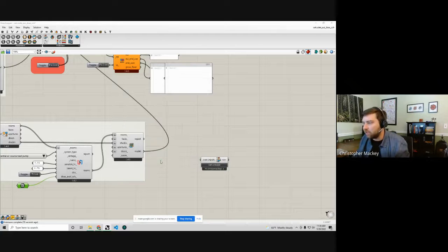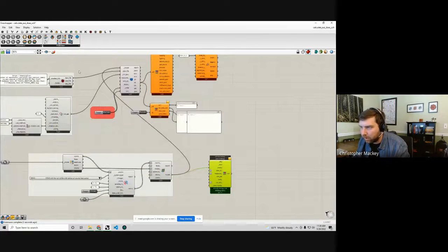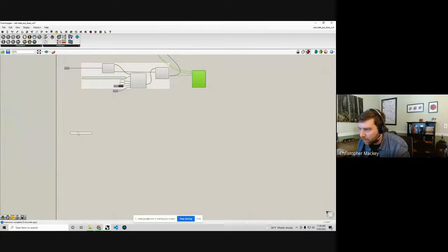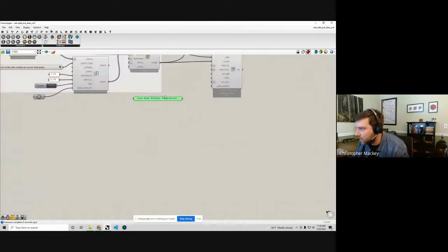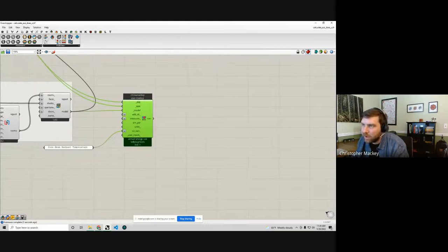I'm going to select this, and I can plug in my model here as an input. I can plug in my EPW file. This is a very similar type of analysis to what I'm running in Grasshopper here with this model to OSM component. Maybe I have another EnergyPlus output here that I want to visualize in the reports I get out of this. I can plug this into the visualization variables for this recipe, and I can just go and hit this pollinate button.